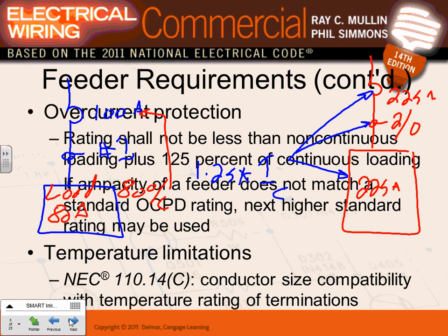This is the most confusing one, the thing that people get confused about all the time. If you have a panel that says 100 amp, do you think you can pull continuously 100 amp out of it? Continuously for 3 hours or more. You can only pull 80% out of this panel. That's why the 1.25 is there. They oversize the panel from the get-go, so you don't get a panel that has 100 amp, but you can only pull 80% of it.